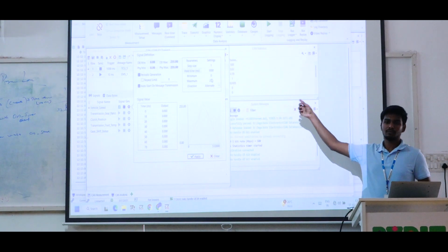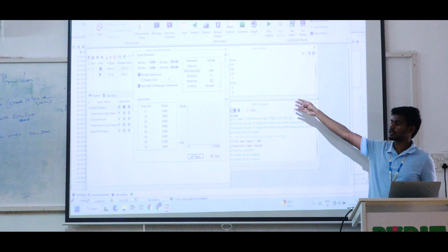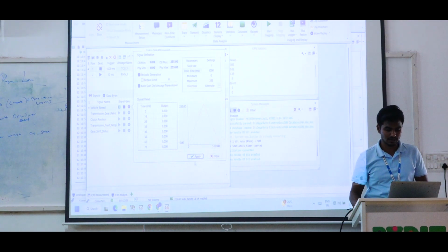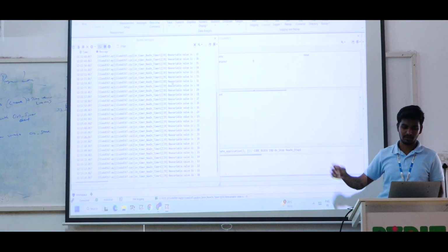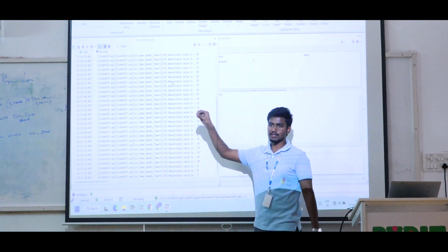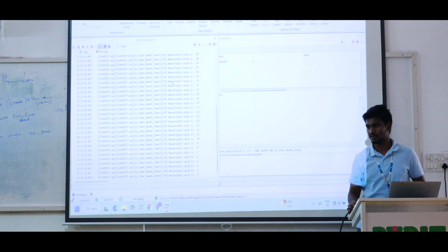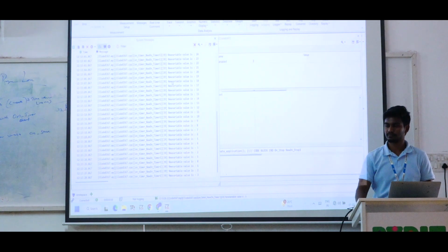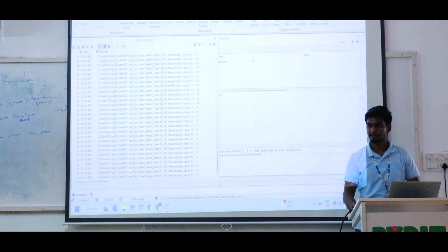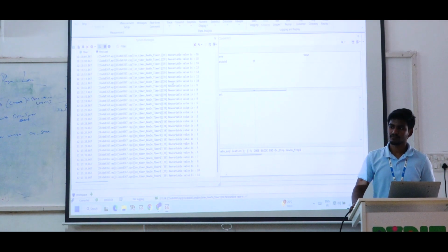Increase the value one by one, but the time you can take is 1 second. So for the next size, you have to take the value as 1 second, so that we receive the same order in the receiving panel, which means in our CAPL scripting panel we receive step by step. Previously we were receiving some random values, but they are not random, it is based on the timer event. In the timer event we set 10 milliseconds, so we received the same values. Now I give a timer of 1000 milliseconds, so after every 10th value it will come. It will calculate the same thing.